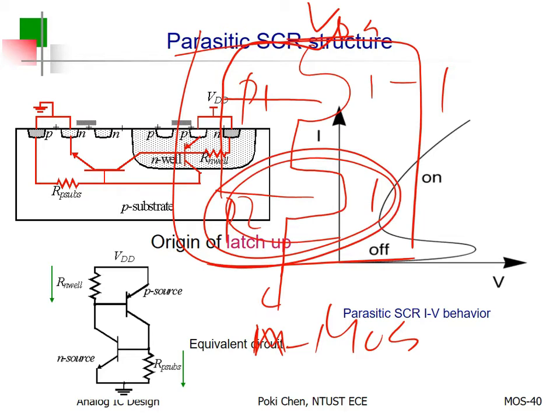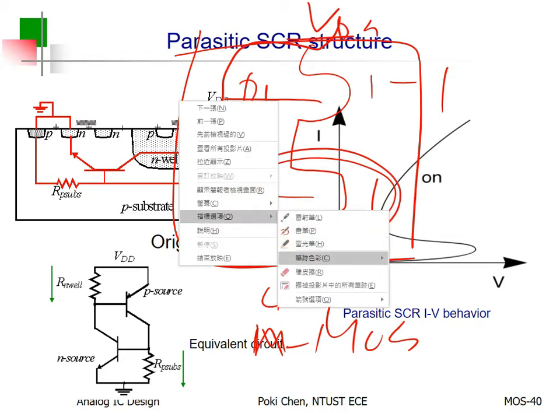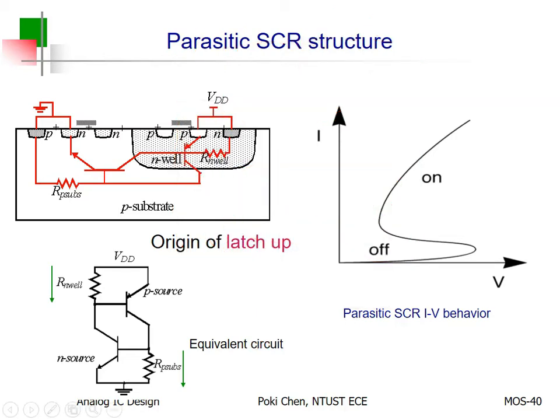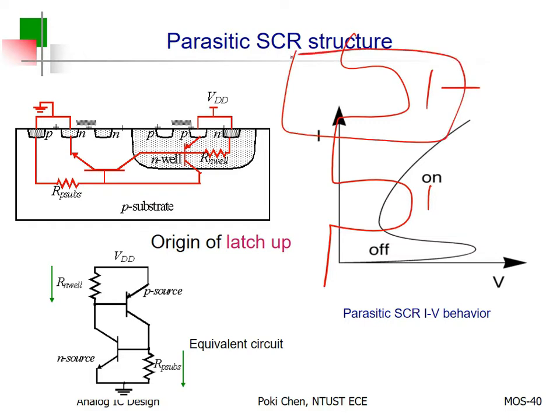All right? So how to eliminate all the body effect for such kind of stacking structure? You need to have separate N wells. Okay? Then you can connect your body to your source. And then his body to his source.